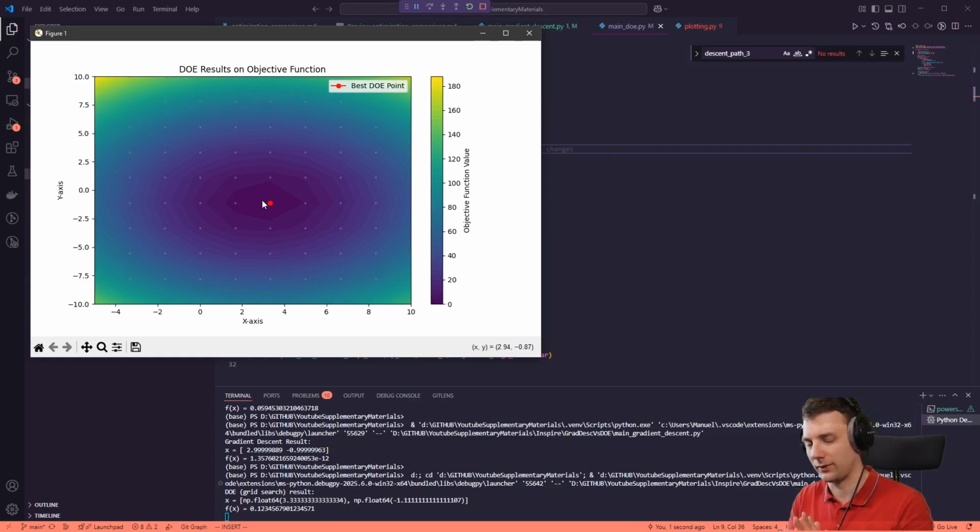Okay, so basically what I want to tell you with this is you have those two approaches. DOE is highly applicable for problems where you have something like a nonlinear surface or nonlinear problem, and you don't really know too much about it. And that's where Design Explorer comes in. And gradient based is when you know something like a relationship between, for example, the stiffness and the element density. For a stiffness matrix, you can derive the gradients, so that's a pretty easy shot to do the gradient-based optimization approach there. DOE, more nonlinear.